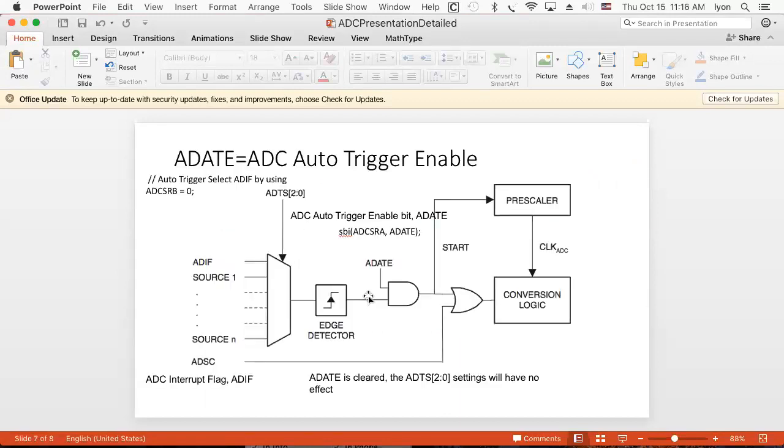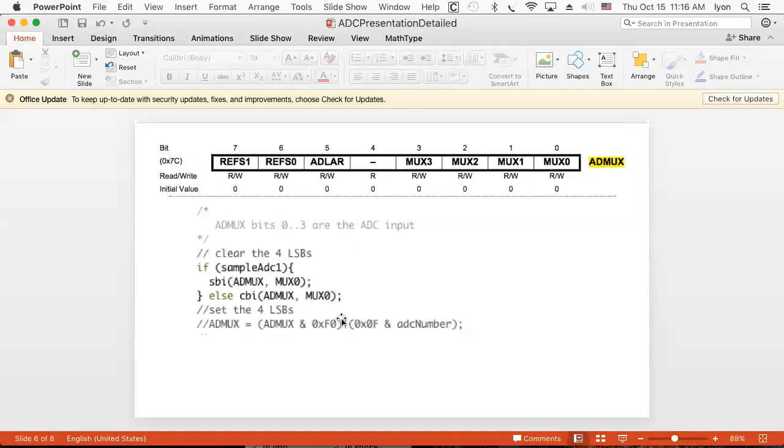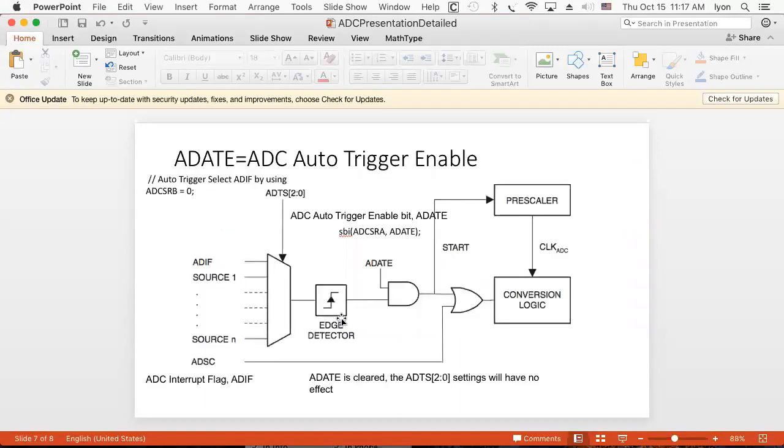And to that point, I should mention to you, when you read the data sheet on this, it says if you have a 20 megahertz clock on your Mega 328P, you have 20 MIPS, 20 million instructions per second. When you have a 16 megahertz clock like we do, you have 16 million instructions per second. So our clock rate directly links to our architecture, which is a single instruction, single data, or SISD type architecture. So if you make this chip faster, it's going to go faster. There's no multi-cores. There's nothing fancy going on. In fact, it's an 8-bit toaster controller.